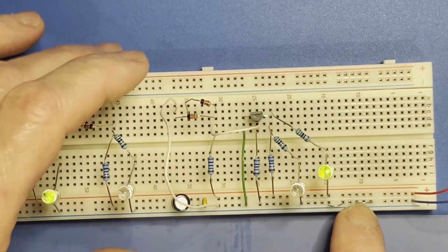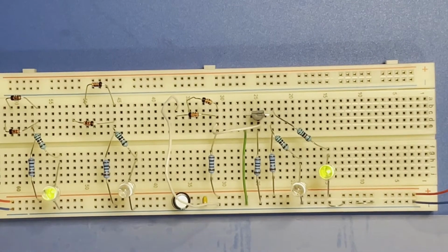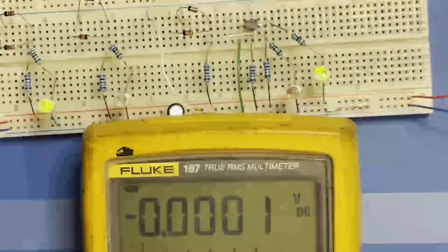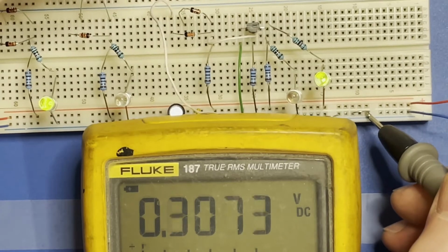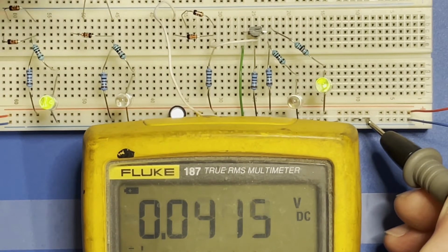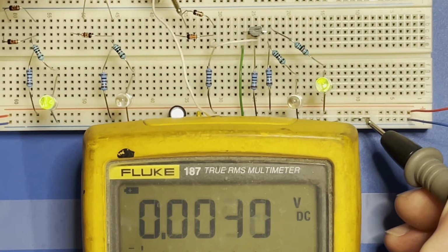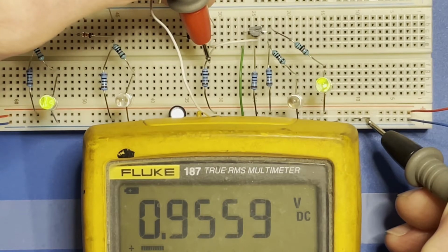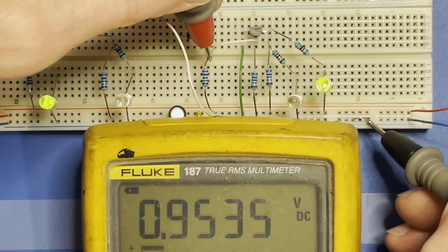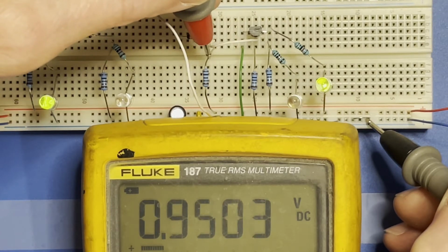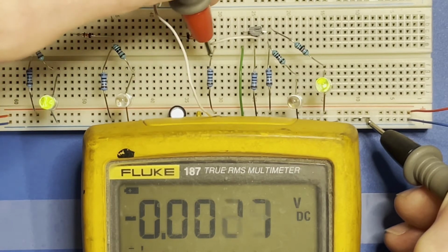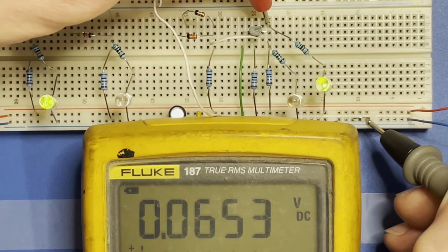To make it actually work, let me just show the voltages first, so you can see why it's doing what it's doing. Actual voltages, just to demonstrate this. Try not to push things out of view again. So, with the inputs disconnected, that resistor is pulling the base up quite high. It keeps going up every time I look at this. I put a bit too much power through that transistor, really. It's a 1K resistor, so it's got about 8 mA through it, which isn't that high. It's not even doing enough to do any harm, really. But the voltage on the base is quite high, and the voltage on the collector is very low.